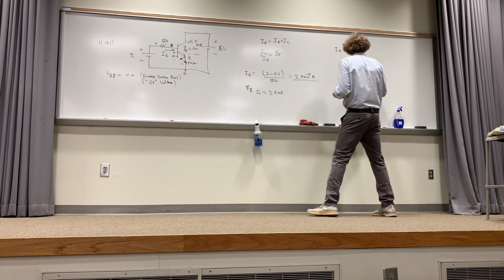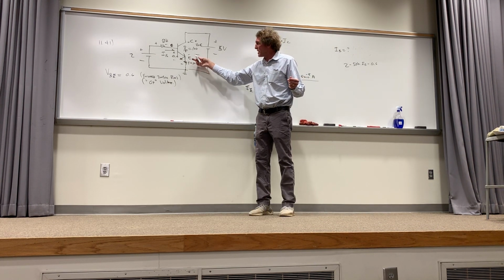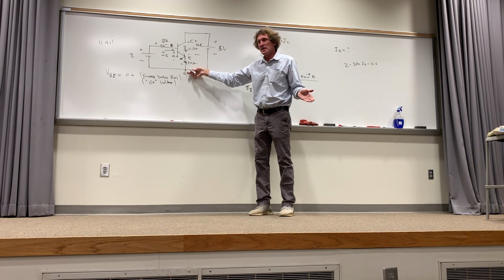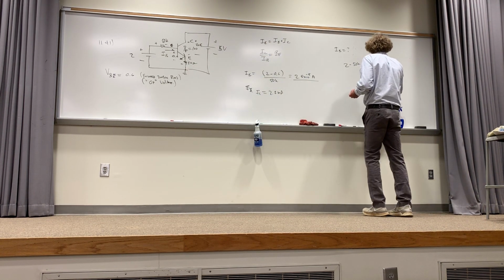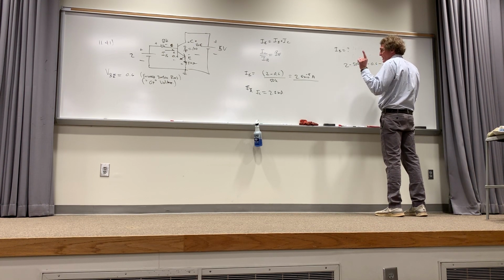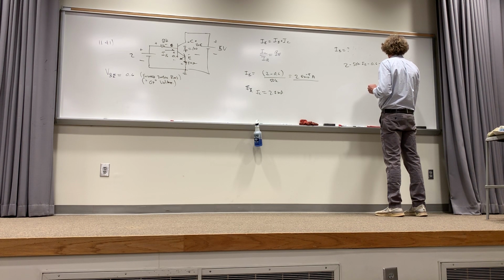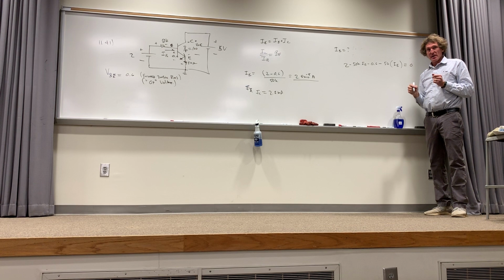So it's minus 0.6. Then from here to here, it's going to be minus, not IB, but IE. Follow me. IE times 50. So it's minus 50 ohms times IE. Now, that's IE. All this equals 0. You agree with me? Short answer.